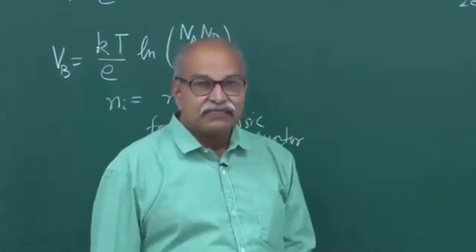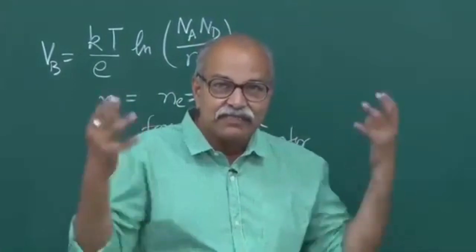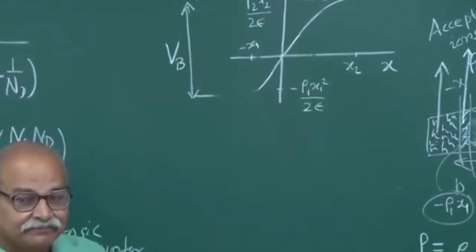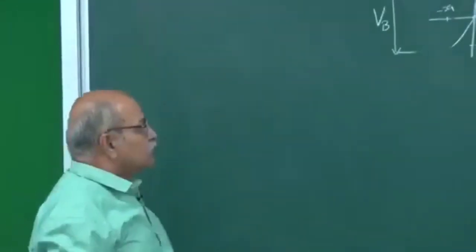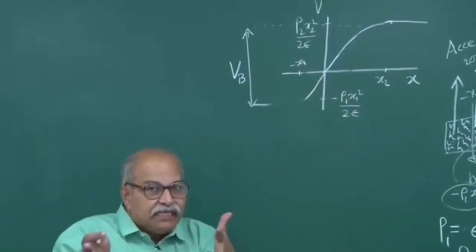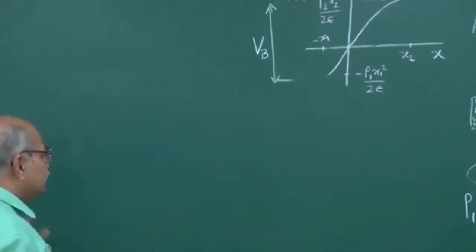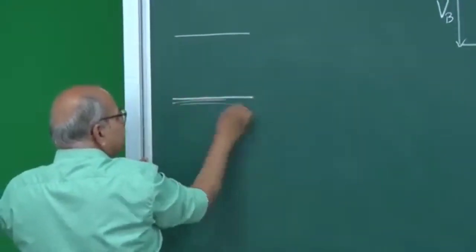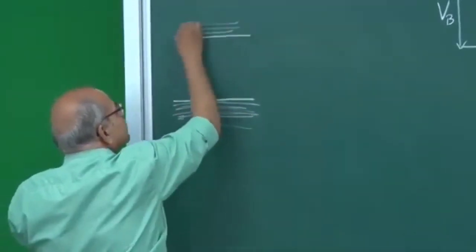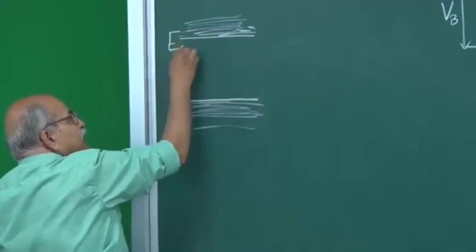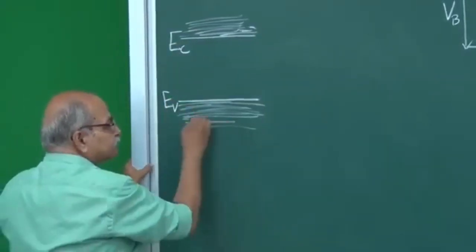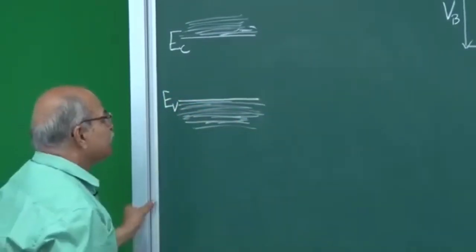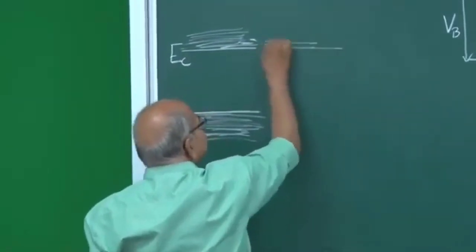All right. So the next thing I will take up is the energy band diagram of this semiconductor, this p-n junction, and the effect of this internal potential difference that is created on the energy band diagram. So if there is no potential difference, you only have a p-type semiconductor and n-type semiconductor in the same original material, then the conduction band is here, the valence band is here, all these energies are valence band energies, all these energies are conduction band energies. So you have this bottom edge of the conduction band here and the top edge of the valence band here. So same is the case with p-type, same is the case with n-type if there is no crosstalk between them. So the other side also is like this, same.